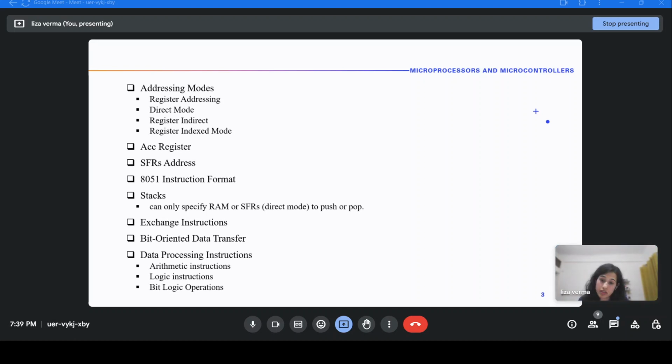The only difference between 8085 and 8051 is that 8051 has internal memory, right? And internal memory is 8-bit wide. Since the stack is in that 8-bit wide memory, the stack pointer is an 8-bit register to indicate the address of the top of the stack.